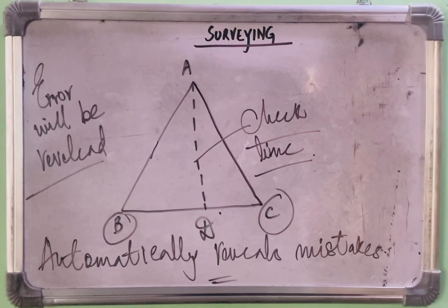If there is only one party, they can take the measurements in reverse direction. And if there are two parties, the same measurements can be taken independently, right? So the survey must be arranged so that the results are checked by office computation and plotting, right?